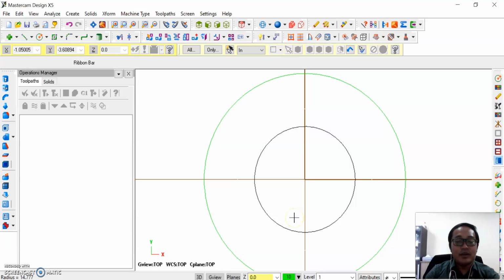Okay, so it will vary depending on the type of drawing that has been determined before this. So if, let's say, you want to change the other colors, the short way is, if you want to change the black color to any color, just select on the black color here. Okay, so you just right click on the system color, select entities to change the color of.